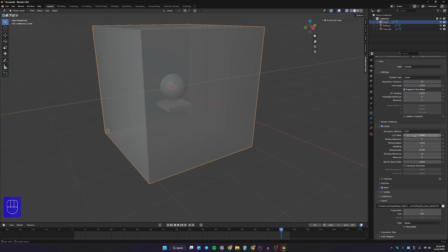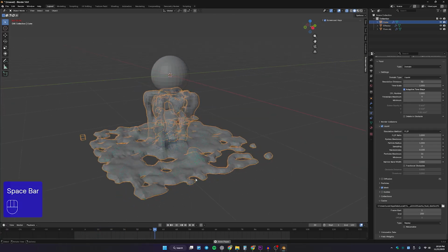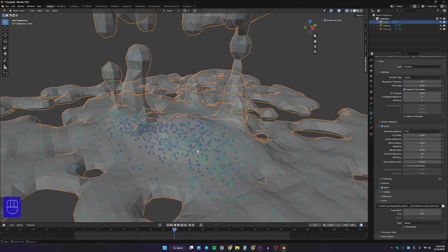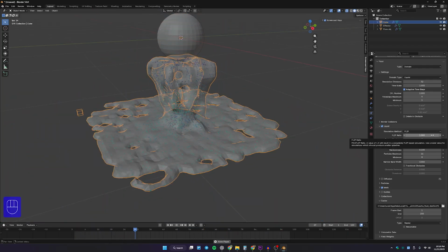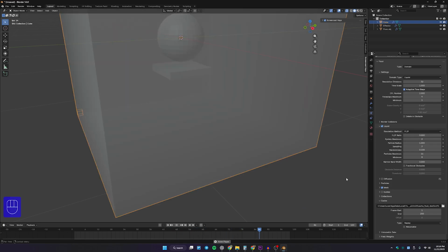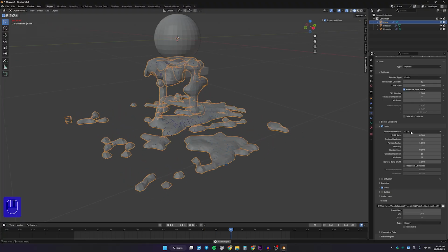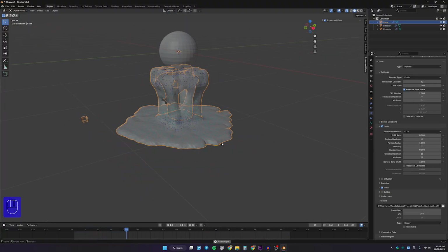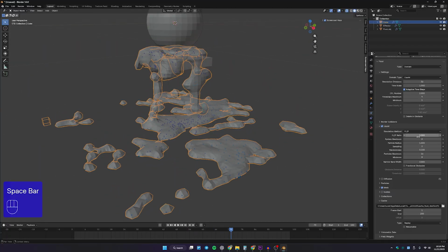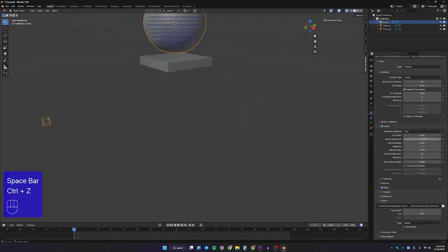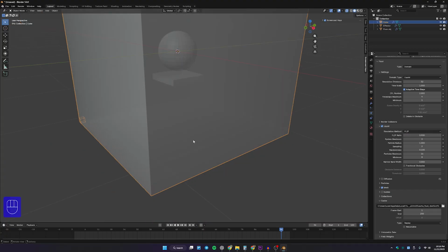So you can go all the way up to 1, which gets you more aggressive fluid simulations. If you look closely, your particles are really aggressive with this value at 1. And if I go all the way to 0, which is pretty similar to APIC, actually I noticed that it is way more stabilized than the APIC itself. Like you can see, it is more stabilized. Right. So I'm going to go back to my original strength. I don't really remember, but let's type in something like 0.9.